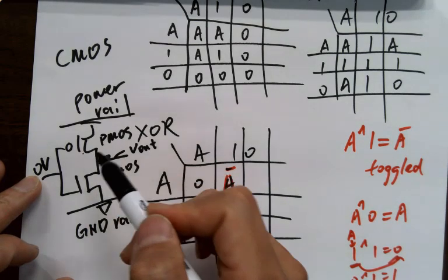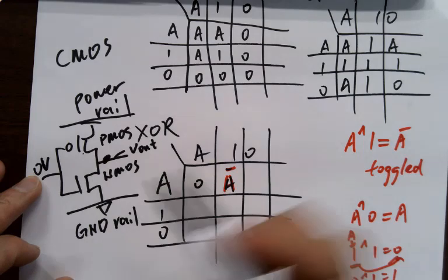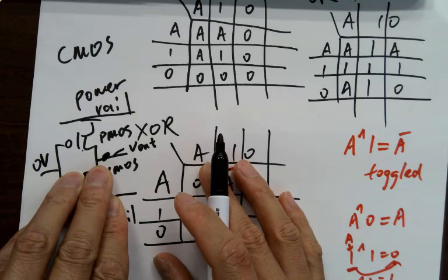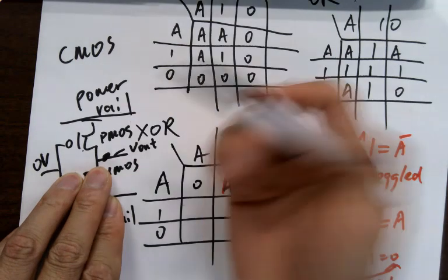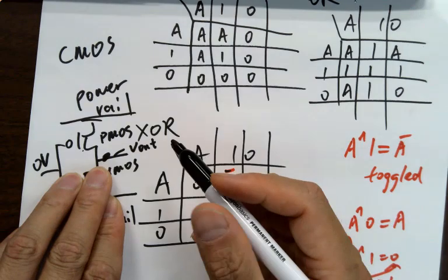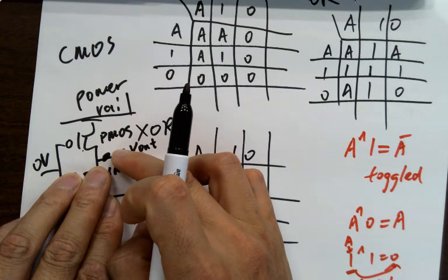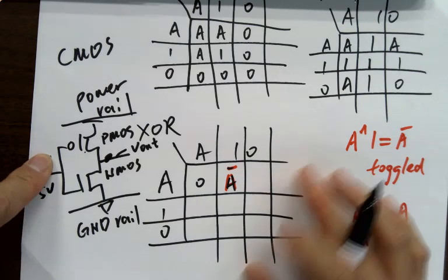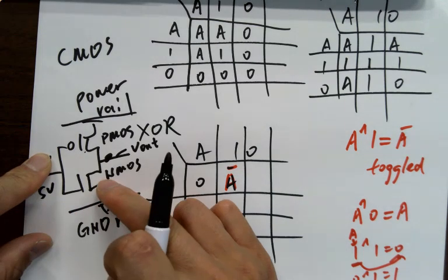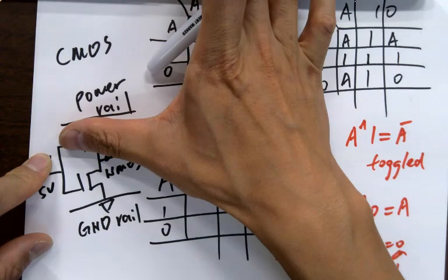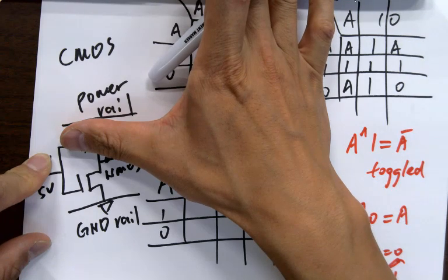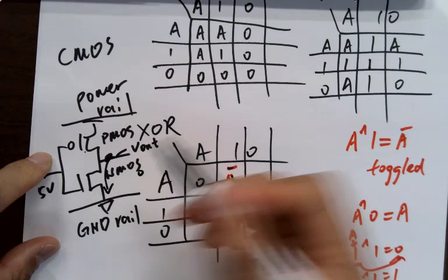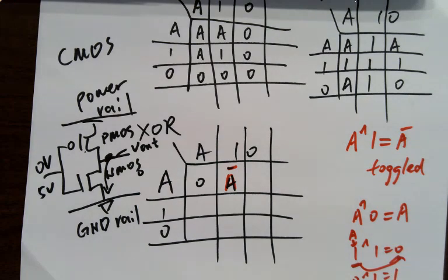It's different from a pull-up resistor, because this one is totally off. It's just a disconnected circuit. Or you can say it's shorted to power. Either way, you're getting 1. Okay? If you give a logic 1, or 5 volts, 5 volts will turn on the bottom transistor, so the top one will be off. So what's going to happen? This one is shorted to ground, so you're getting 0. That's how the inverter works in integrated circuits.